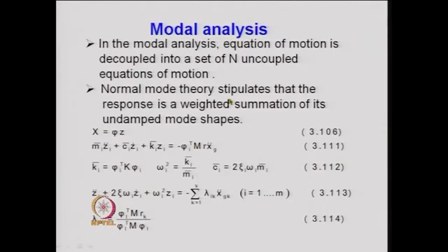That means, for the entire structure, for the ith generalized coordinate, we will have only one time history of excitation, which will be called the generalized excitation for the ith mode, and there the effects of the different excitations at different supports are all summed together to find the time history of the generalized excitation at the ith mode.